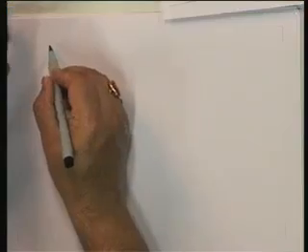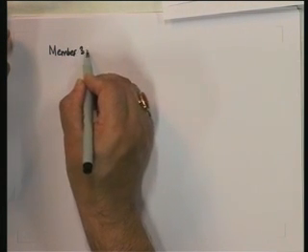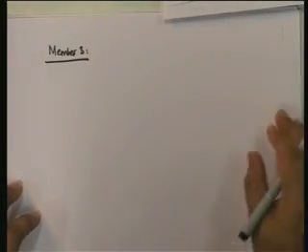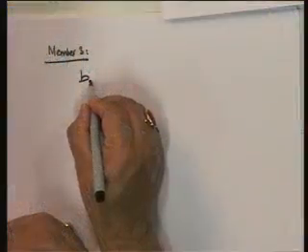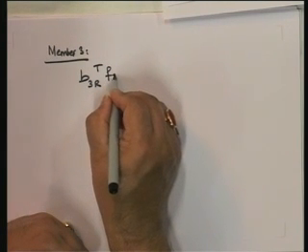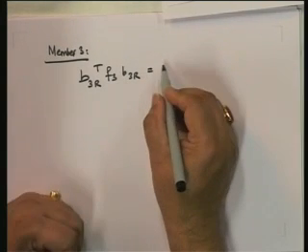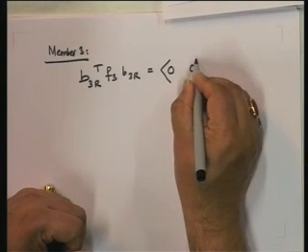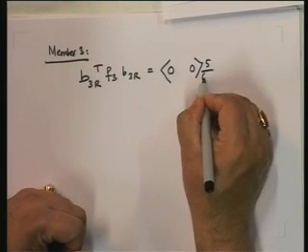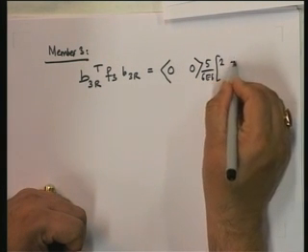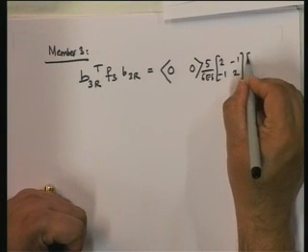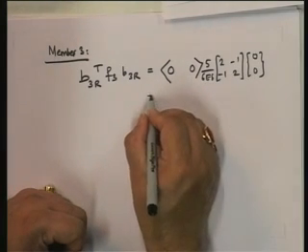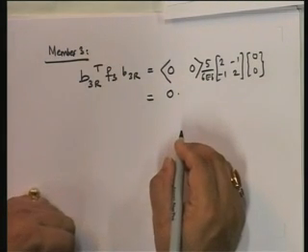So now finally we have to do it for member 3, and let us see what we get for member 3. Once we've done it for all 3 members, you will see that we can add up and actually solve the problem. Okay, so let us look at B3R, F3, B3R. This is equal to B3R is equal to 0, 0, 5 upon 6 EI, 2 minus 1, minus 1, 0, 0. And without much ado, we can see that this is going to be this.